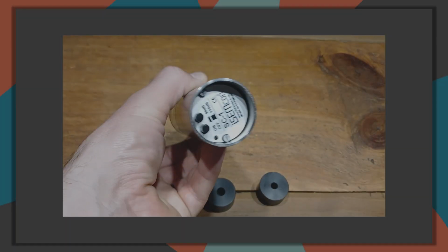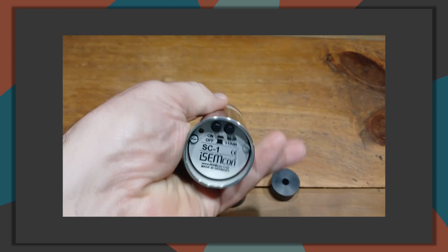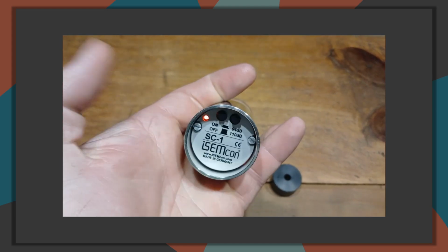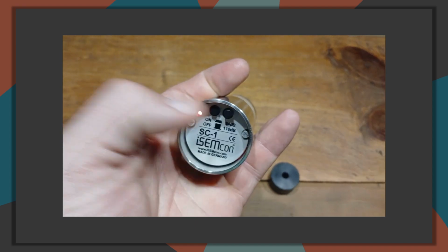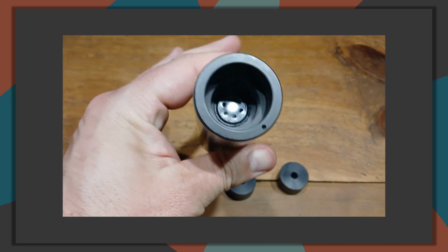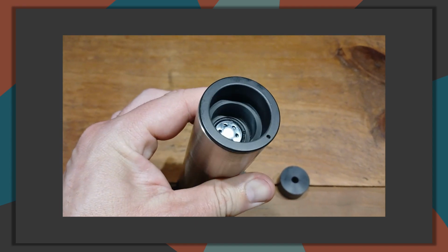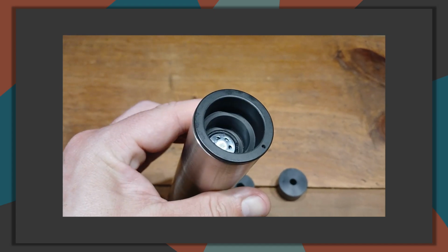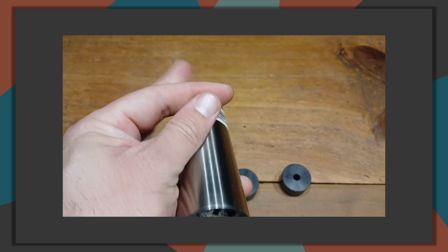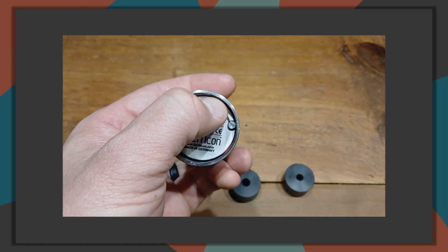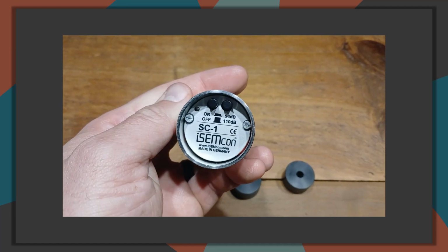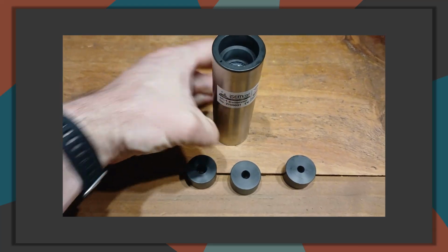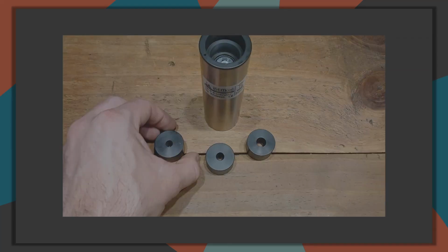To do it correctly, you'll need a standalone microphone calibrator that plays a test tone at a known sound pressure level for the measurement microphone to be inserted into and calibrated in Smaart. I have the ISOMCON SC1 piston calibrator, but they all work on the same basic principle. It has a built-in loudspeaker that plays a sine wave tone at a specified sound level.